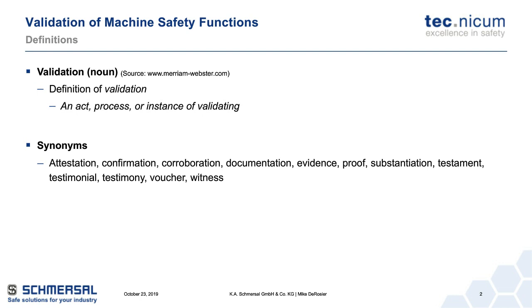When you look at some of the standards today, probably one of the ones I'm going to reference most would be ISO 13849, and specifically Part 2 when it comes to validation, because that standard's written around that. It's complementary to 13849-1 with the safety functions themselves for machines, when we talk about the safety-related part of the control system. But when we think about validation, we're starting to see it pop up in other standards over the last several years as well.